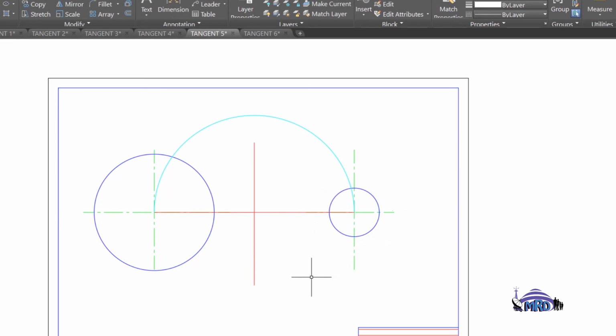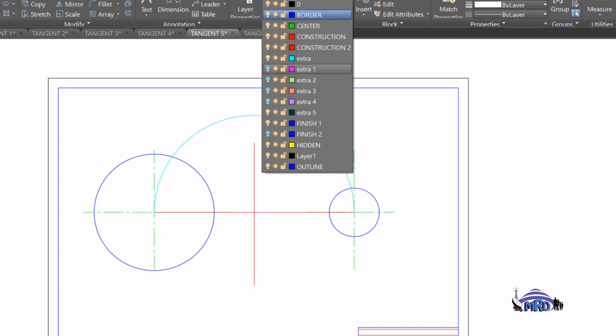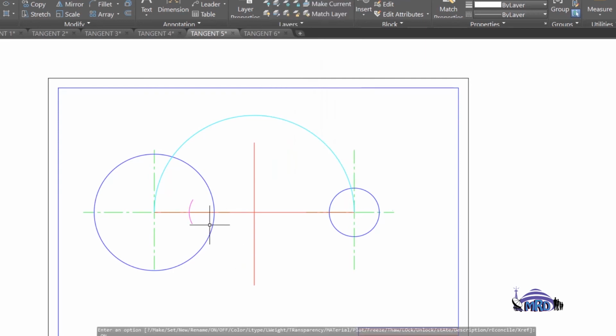So if you were drawing, you would open your compass to 25 and you would take that radius and you would mark that radius inside of the bigger circle. So you would start on the outside by the circumference here and you would drop that radius inside of the bigger circle. So once that is done, you have an arc or a little curve at that point. So this is 25 millimeters in here. In essence, what you're doing is subtracting the radius of the smaller circle from the radius of the bigger circle.